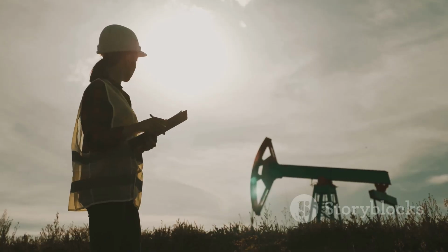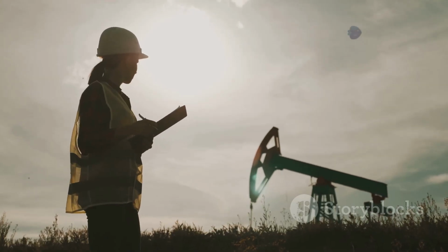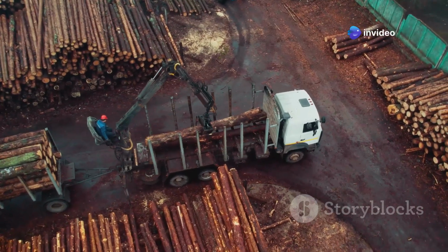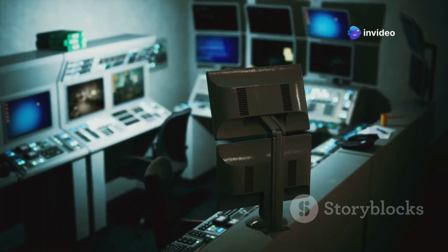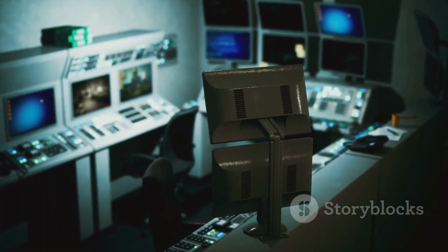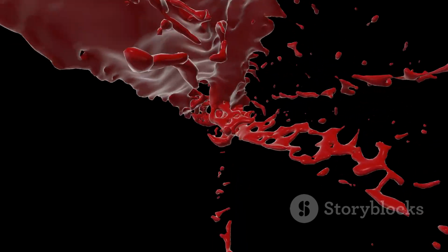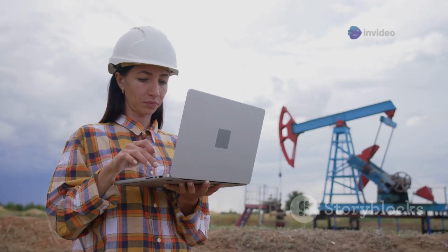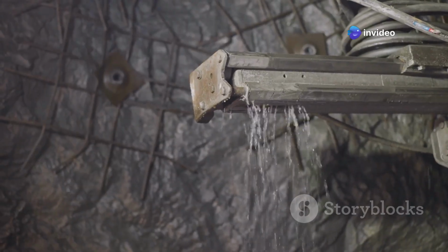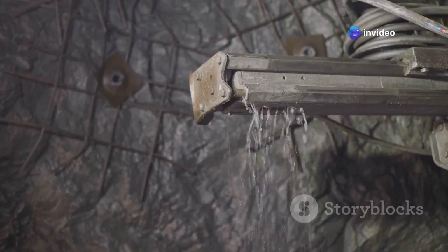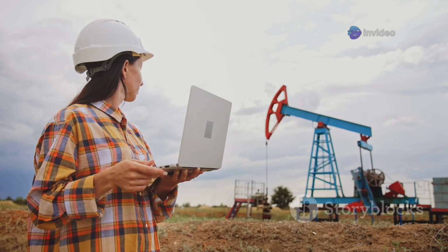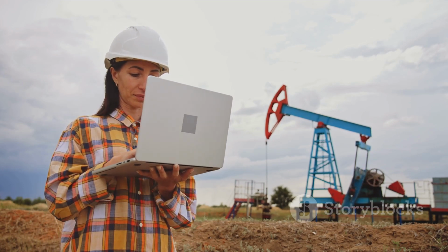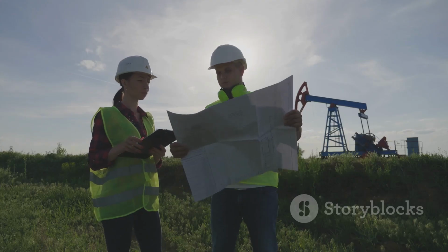The utility of well logging does not end once production begins. Specialized logging techniques, known as production logging, are used in producing wells. These logs help monitor what is happening downhole. They can track the movement of fluids within the reservoir. They can identify which zones are contributing oil or gas. They can also detect problems, such as unwanted water production. For example, if a well starts producing too much water, production logs can pinpoint where the water is entering the well bore. This allows for remedial actions.